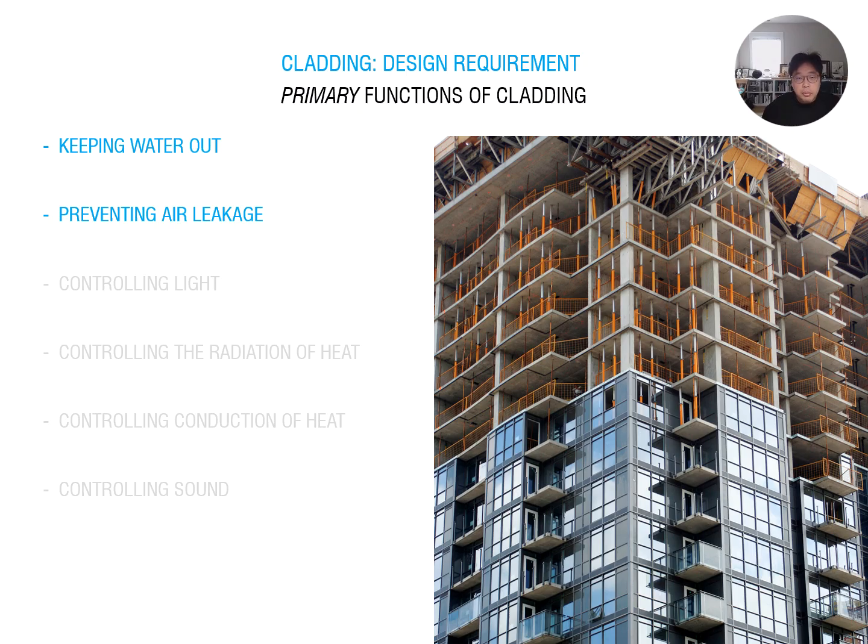And of course, you have to prevent air leakage from your cladding, the unintended passage of air between indoor and outdoor. Air leakage wastes the conditioned air, which means a loss of energy through this gap. That's why you have to seal tightly between the window frame and glass, and between the window frame and the floor and wall assemblage. We talked about this assemblage already in our section detail, but we're going to talk about the protection one more time in 4450 class.